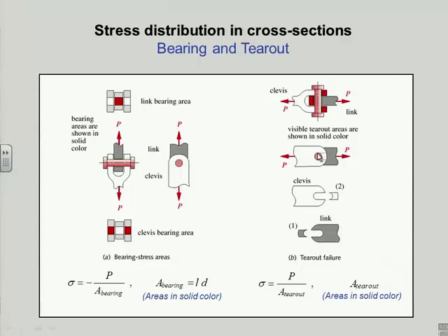Do I take it from the center line of the pin to wherever it happens to intersect the radius? Well, I could do that, but that's fairly cumbersome to deal with. And again, at that outside top and bottom portions on the diameter, it has no grip on the part to push on it, really, right? So we average it out. We say, let it be the distance from the edge of the pin to the edge of the outside of the part. And we call that the tear out area. And that makes it a simpler calculation.